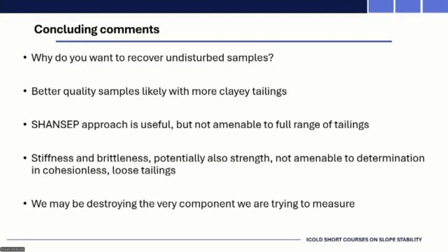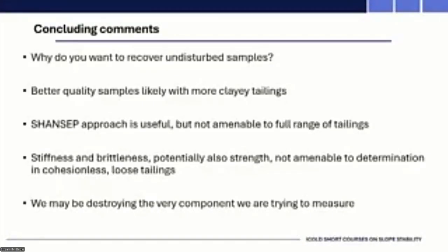Now, there's no doubt that we're imposing more strain than that when we're sampling. And there's a paper from the mid-1980s, I think by Baligh, called the strain path method, where he shows exactly that. And in fact, talking to people subsequently, they reckon that's an underestimate of the strain imposed during sampling. So, as SW has already said, it's a real challenge.